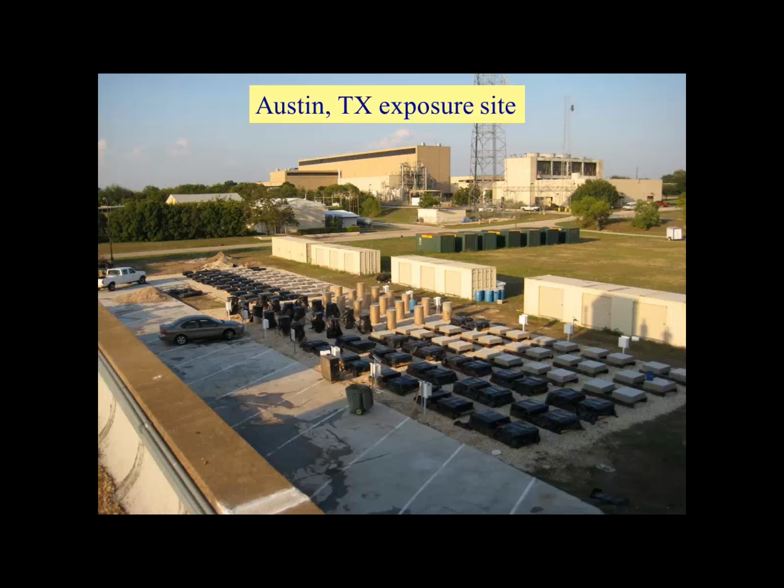The challenge with field structures isn't so much the age of the structure, but it's the ability to get the lithium into the structure. And our experience has not been very favorable with regard to getting sufficient depths of penetration of lithium, with the exception of the electrochemical technique, which I described. But lithium itself is a very viable technology for controlling ASR, generally much more suitable for new concrete as opposed to existing.